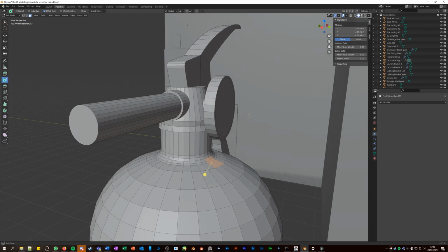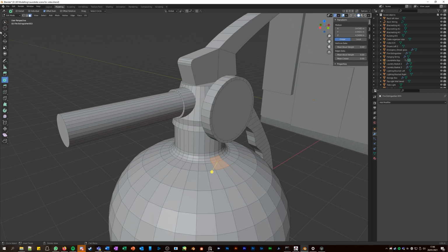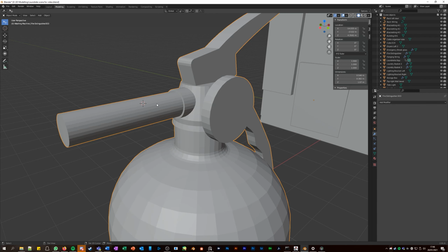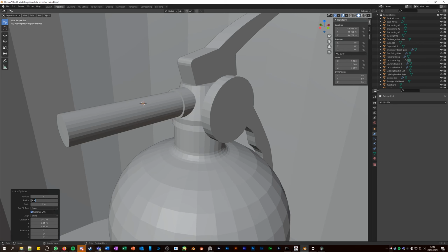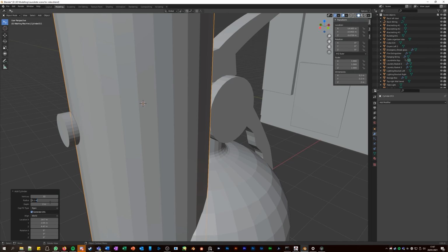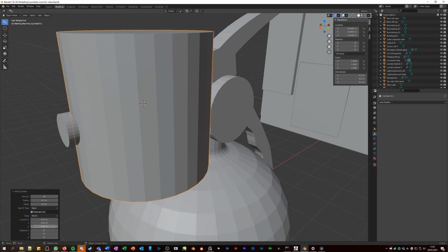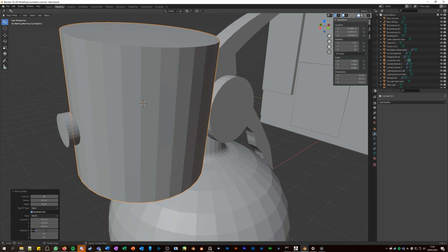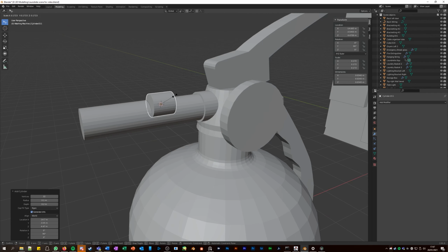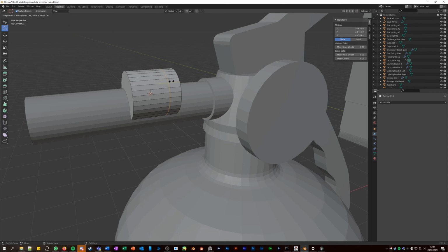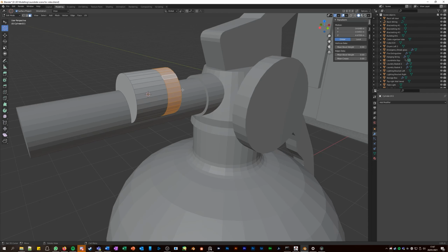So with this, this is another cylinder with an extruded face. So I'll get out of edit mode. I bring in a cylinder here. Bring the radius down to 0.1, depth down to 0.2. Then you can rotate it around the y-axis, 90 degrees, scale it down, whatever. Then you can add a loop cut around here, and then select these faces. So if I go into face select these faces, and you can extrude.